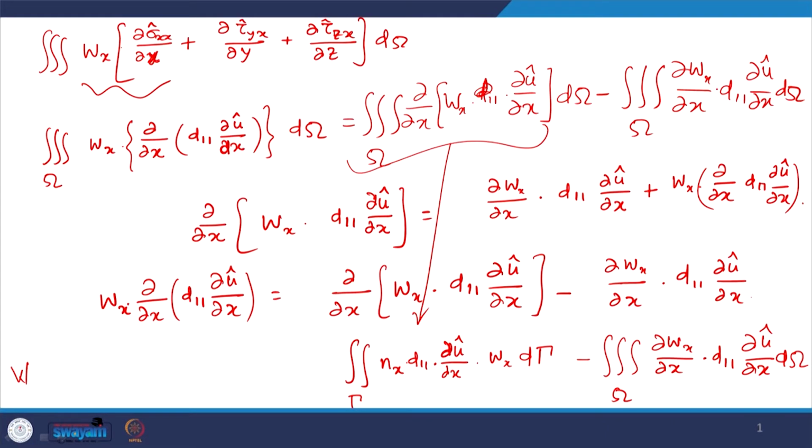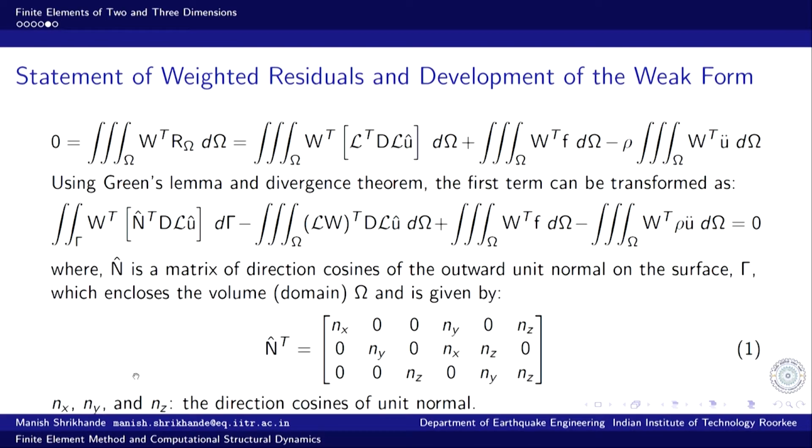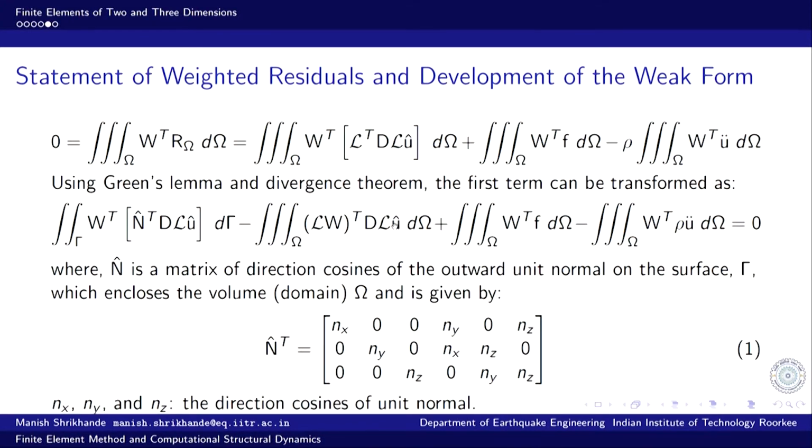W is three dimensional. I said this is a diagonal matrix of 3 weighting functions W x, W y, W z along the diagonals. So, it appears in its natural form on the boundary term without any derivative. So, that implies the primary variables are the unknowns of the problem. So, the unknowns of this equation are u.